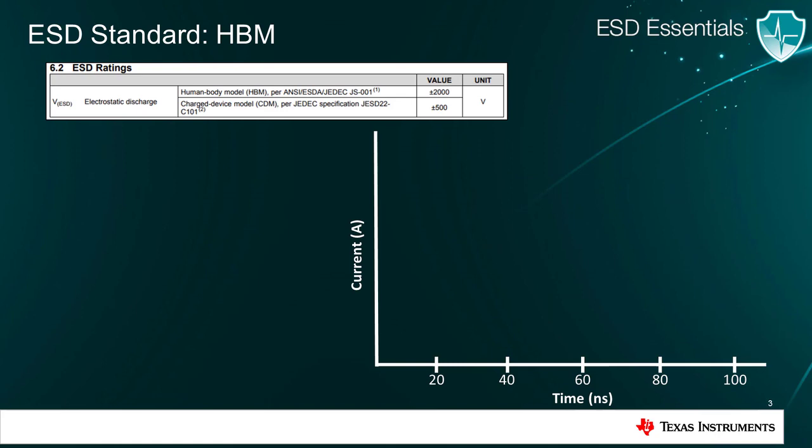Almost every analog and digital component has a section in their datasheet that shows the device's ESD rating. Oftentimes, circuit designers will mistakenly look at this section and automatically assume that the device has enough ESD protection to survive real-world use. However, this is not necessarily true because it's important to understand what standards are being used to measure the ESD. Here, we'll go over some common ones that you may see in datasheets.